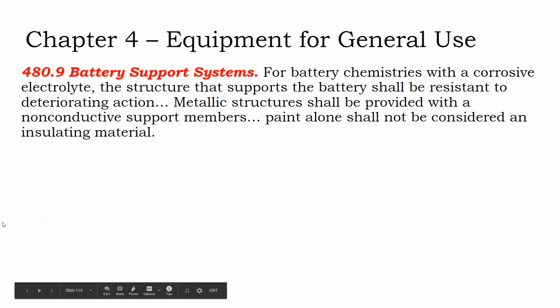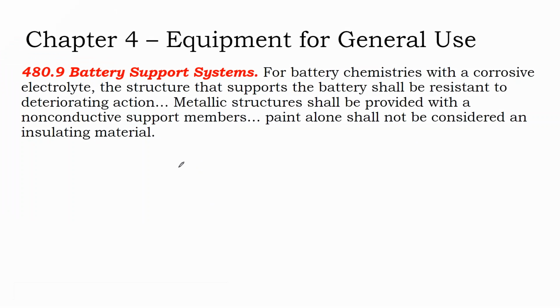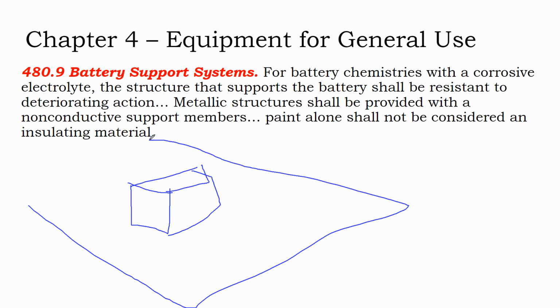The battery support system itself deserves a little bit of attention. So there's a couple of times when you can have, let's say here's your battery bank, and you just want to put it on a concrete slab and just set the battery right on it. The structure that supports the battery should be resistant to deteriorating action.